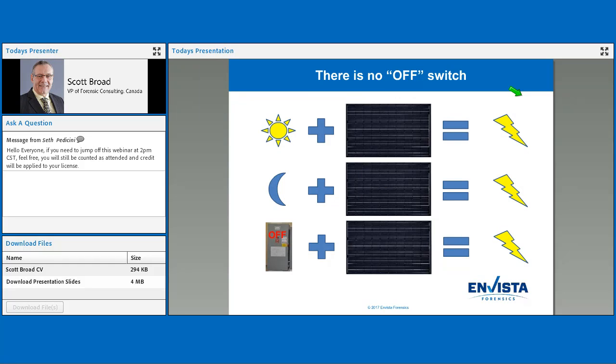Basic maintenance. I've got another question about basic maintenance, which is a great question. For the O&M maintenance on these things, we see the reputable companies going from system to system yearly, and the initial work they do is an IR scan. We have a division now that's setting up IR scanning done from drones, because to manually scan, say, a solar farm would take you a week, where our drone systems are flying overhead. They're identifying hot spots quickly, and then they're manually investigated from that spot. So that's some of the systems that we're seeing.